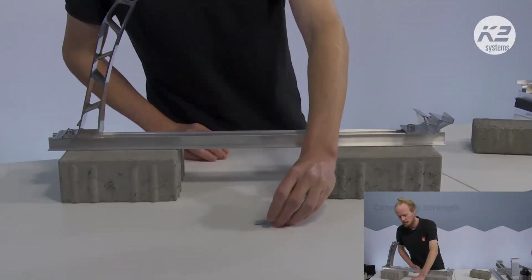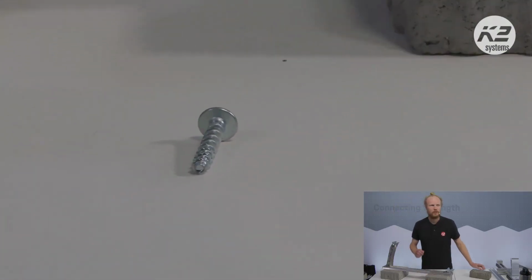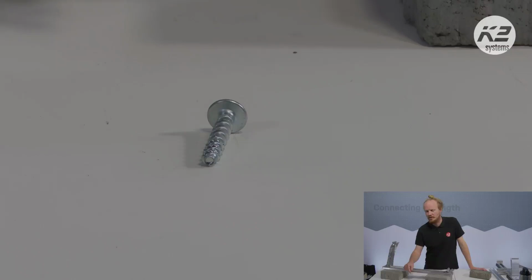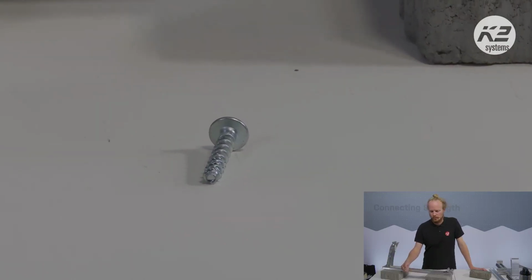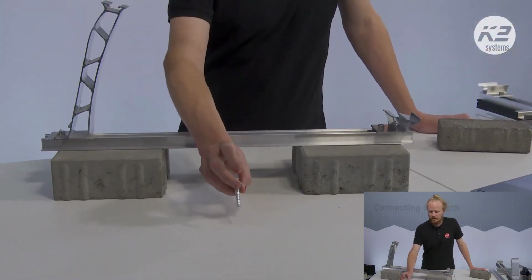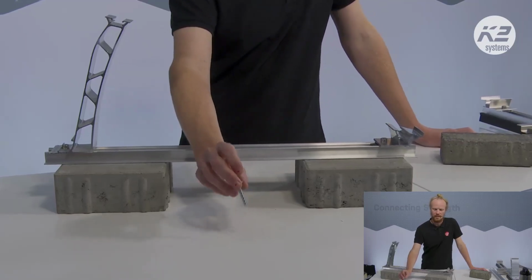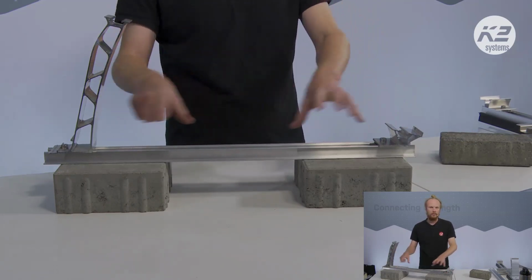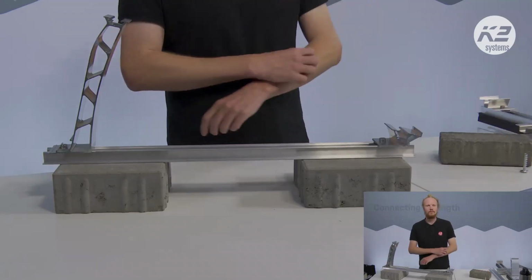And those screws are Monty screws. These come from one of our suppliers. It's a concrete specific screw, designed for screwing into concrete. We also use a very similar one for our ground mounted systems. They're designed for really high load situations and are very, very sturdy. You can buy a box of these, or however many that's required, and you screw them into the rail wherever the base report gives it to you.